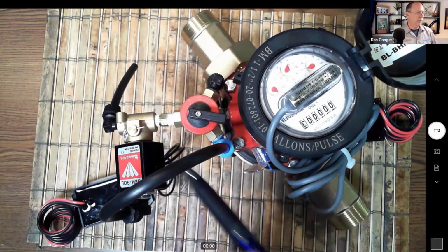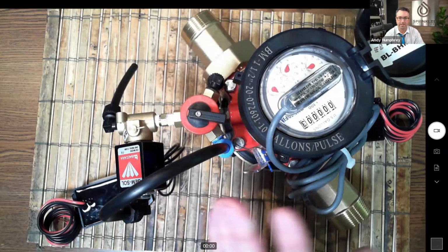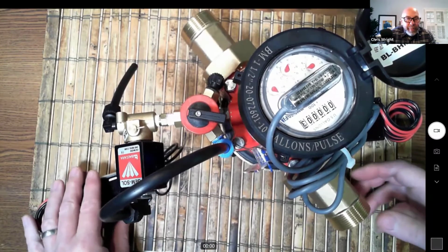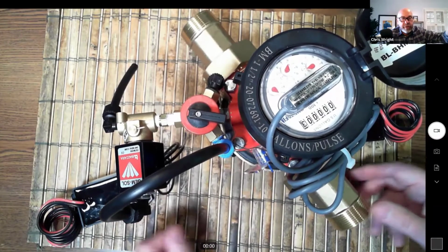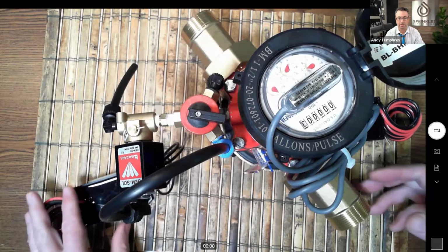Mm-hmm. You can switch that up to open up the solenoid, just like you would on turning the solenoid on a normal irrigation valve. It's very fragile. It helps to exercise it periodically as well. Just turn it as a maintenance principle, so it doesn't jam up or get caught up, because if it jams up and you force it, then you can break it off, and then you've got a problem.